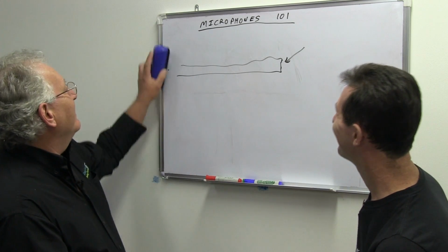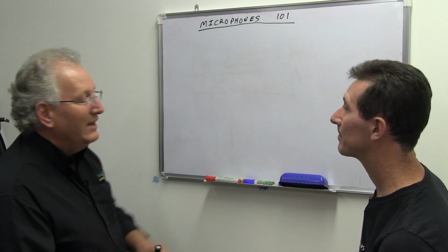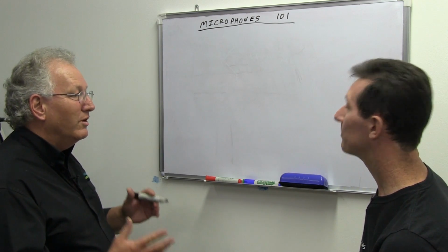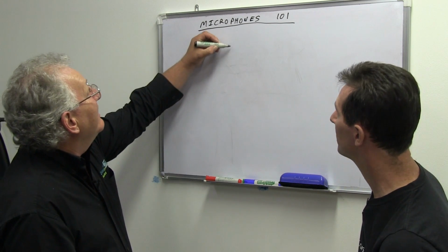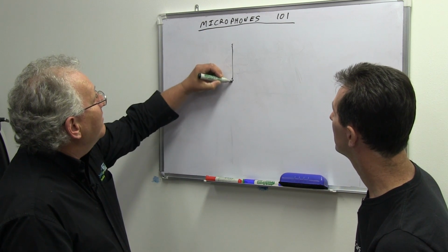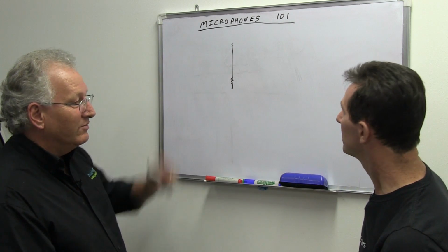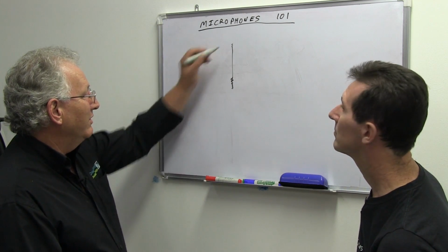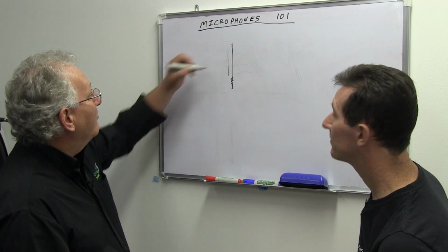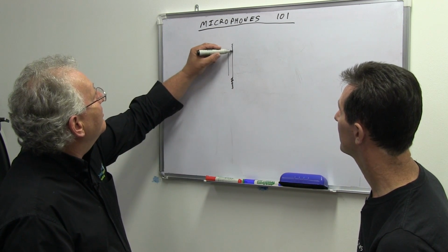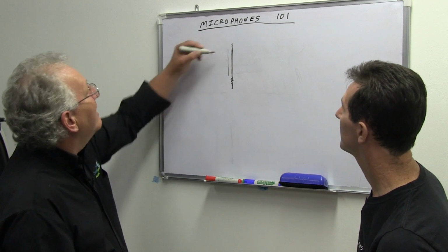The big technology that's in use these days, though, is the condenser mic or electret mic. An electret mic's a variation on the condenser mic, effectively the same. You have your diaphragm. Notice I've drawn the corrugated edges so that it can actually flex, although that might not necessarily be there, near a parallel plate. And what we're sensing is the capacitance between usually a gold sputtered film on there and a metal plate over here.